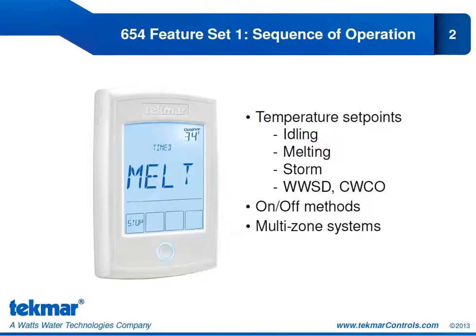What is the idling operation? What are those set points? Same for melting. And we'll introduce you to the storm operation, which is a new temperature set point for the TechMar SNOMELT Control 654. We'll look at warm weather shutdown and cold weather cutout. We'll look at different on-off methods. And lastly, we'll look at multi-zone systems.